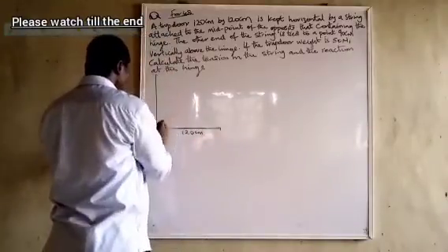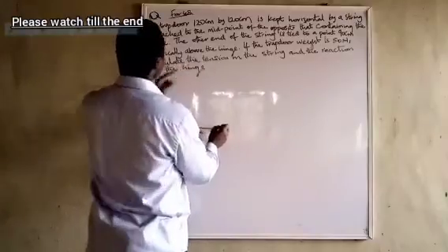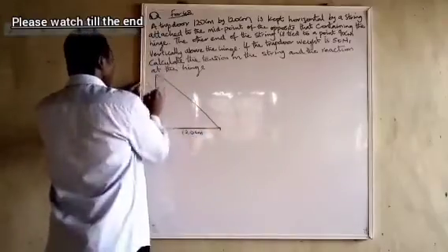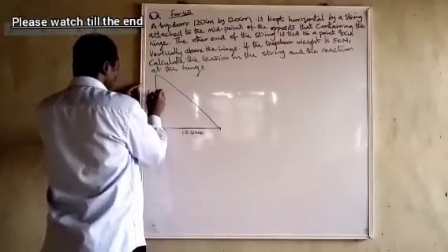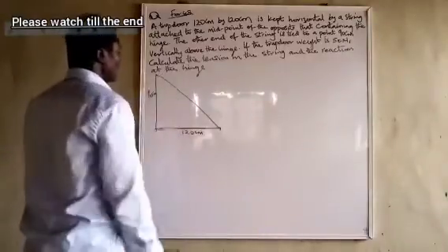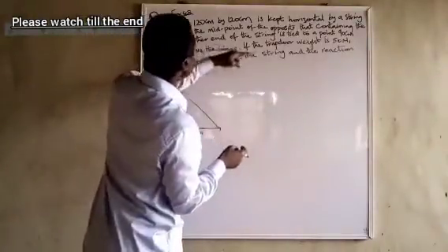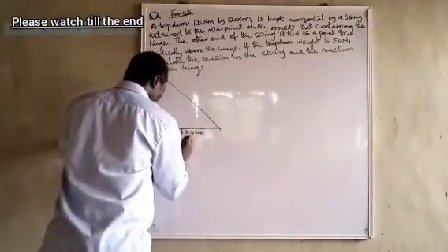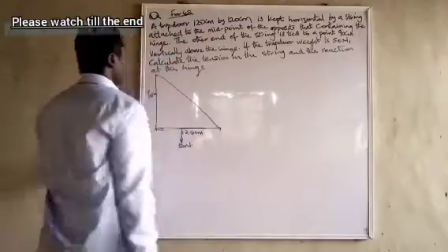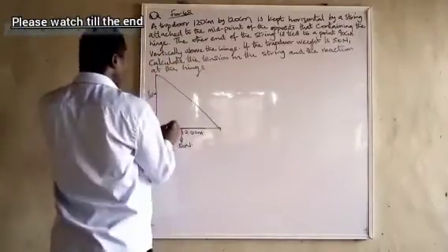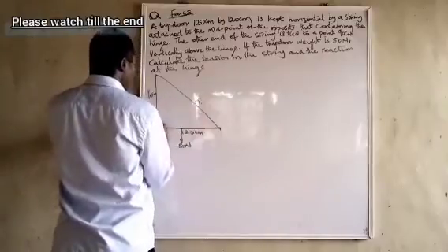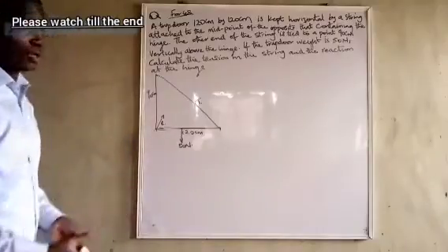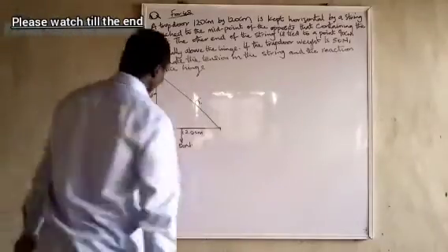Which means that this place to this place is 120 centimeters and it is wide, but we don't need that place. And a rope is tied at this point, and it's attached to this point. We are told that this place to this place is 90 centimeters, and the weight is 50 Newton. Then we have to find the tension and the reaction here. We can use moments to calculate this, and we can also draw a triangle of forces in equilibrium to calculate it. Let's see how we can go about it.